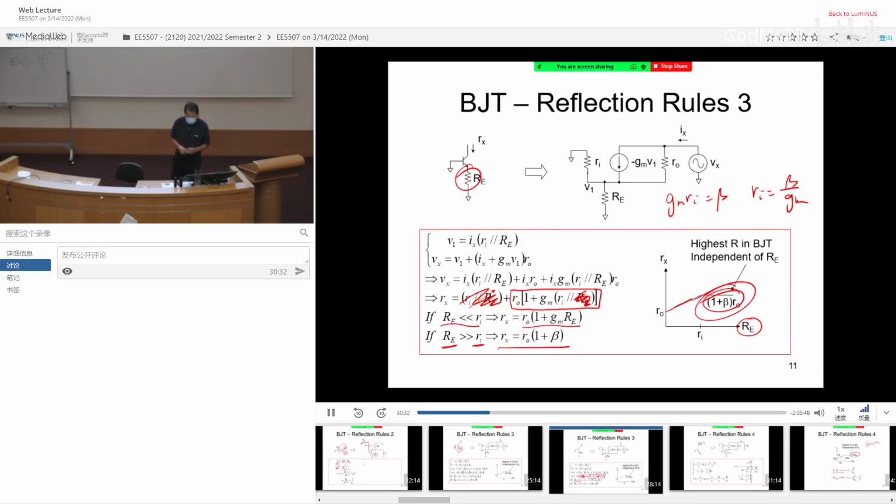Now, I know some of you are actually my undergraduate students, so you probably see this already. So here, in order not to bore you, I try to bring some new insight. These are probably something that I never talk about because for undergraduates I don't need to. But these are the things that people pay attention to when you look into IC design. I want to cascade many devices to boost the output resistance. But why do people not do that for BJT? Because of this.